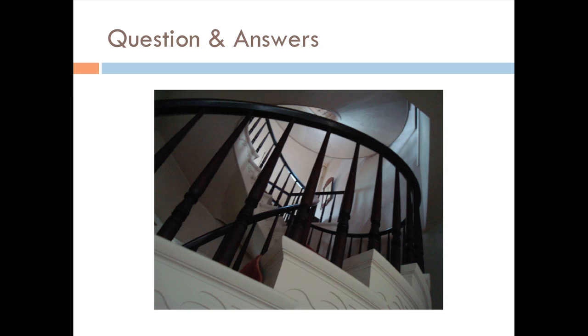A misconception would be not so much water getting into the building, but water being able to escape outward from the inner core. Because as we're all here in this room, we're releasing moisture out from our bodies, and these walls, to some degree, would breathe if they were uncoated with anything.